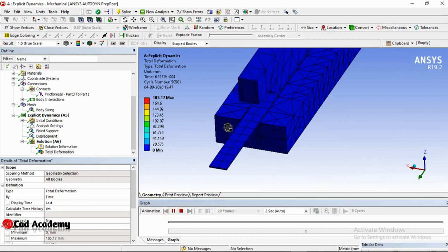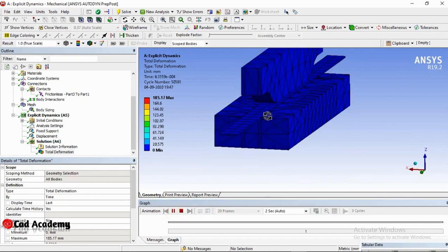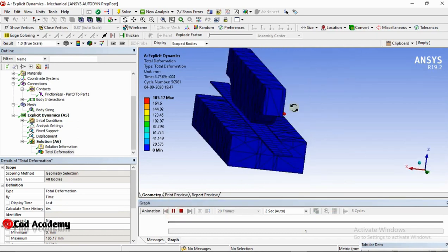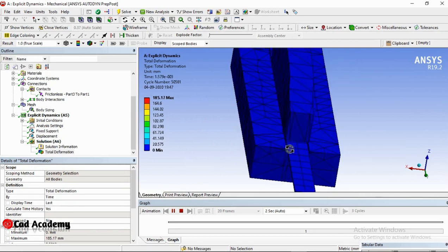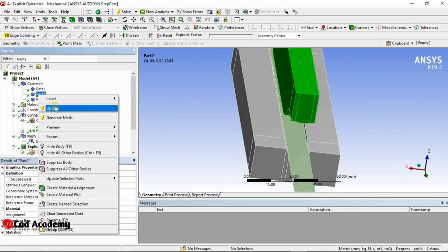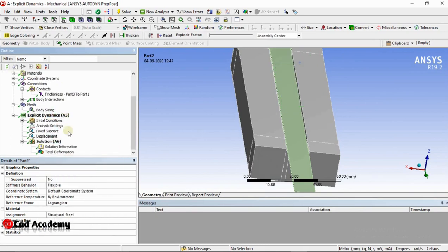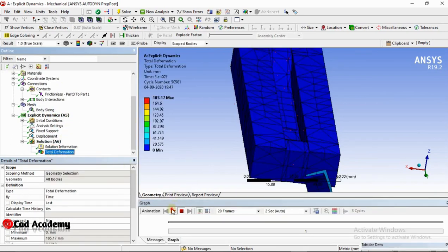Means this operation is not possible. You need to select a much higher strength material for this. Structural steel is not enough material for this die. You can select a much higher strength steel material. I am seeing how the plate forms.